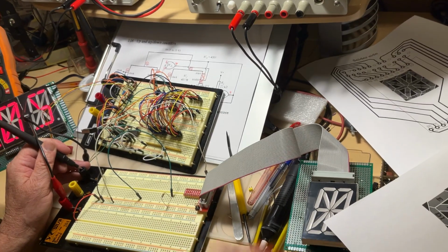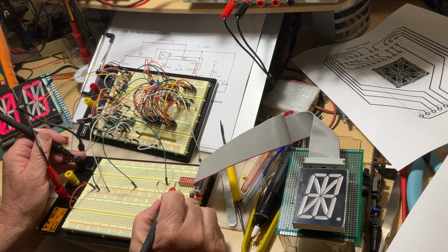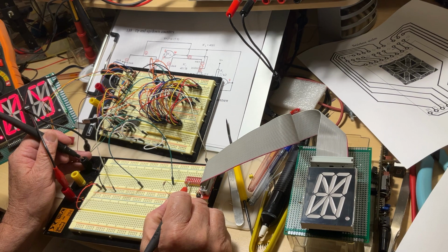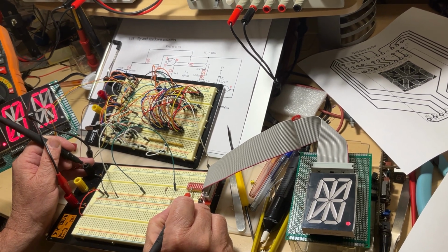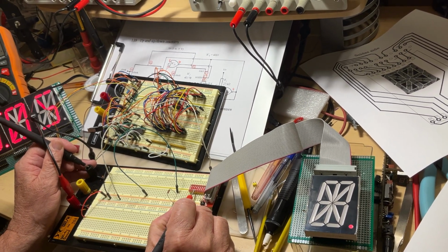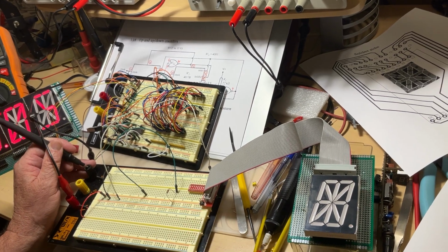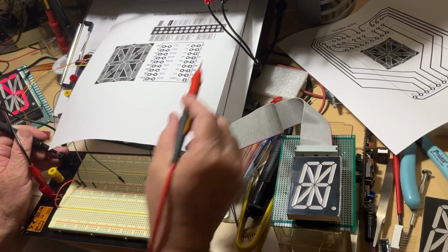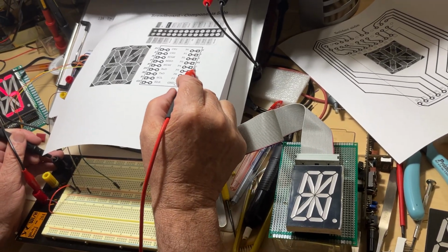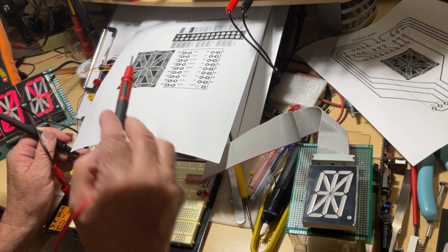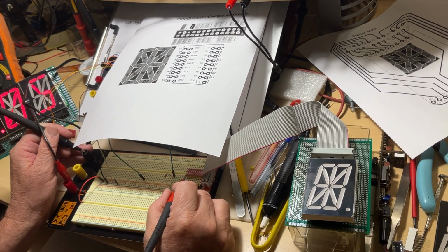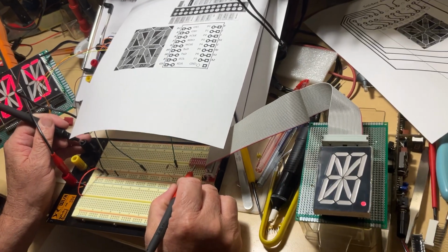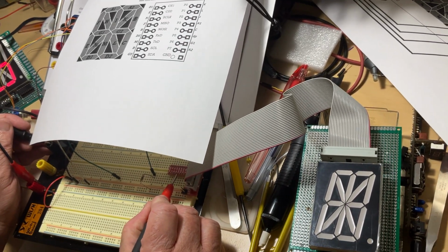Okay? So, sorry for that. 1, 2, 3, 4, right here. So you can see the decimal point is lighting up. So you may think, oh, that's okay, so far so good. Let's identify another one. On top of the decimal point is the C. Segment C is right here. But if you try to do it, the fifth one, 1, 2, 3, 4, remember this is the decimal point, the next one, you try to do it and you don't see it.